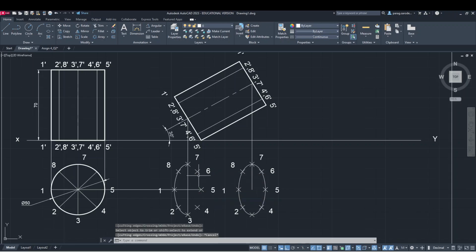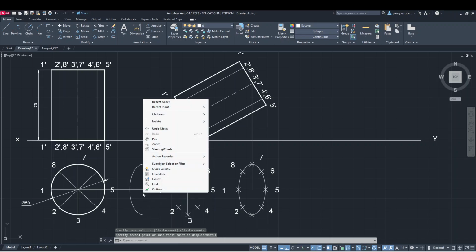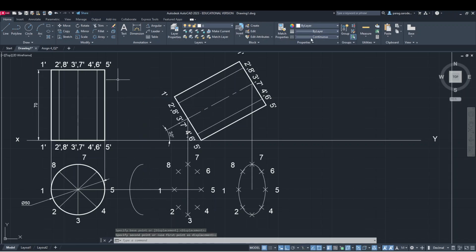And then what we will do, we will overlap it again on this side, or what we can do, this needs to be moved. So let us move this base to another suitable place. So let us take it here, and we will draw an ellipse by taking the hidden line. So let us take the ellipse here. This is our center point. So let us select the center point. Let us select the end point, and this. Now this is the part which we wanted, and these parts need to be removed because part of the ellipse is visible, part is not visible. So let us trim this.